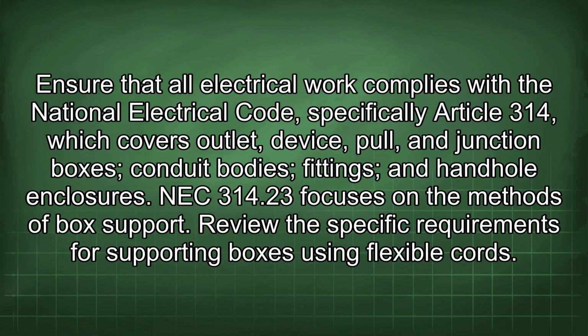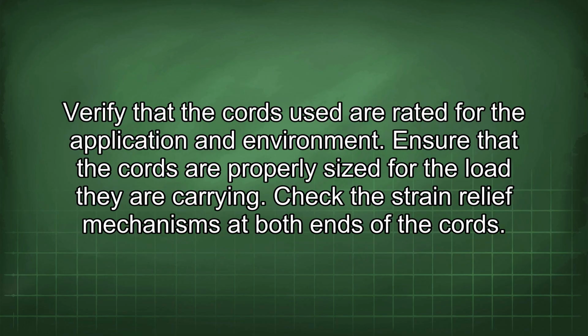NEC 314.23 focuses on the methods of box support. Review the specific requirements for supporting boxes using flexible cords. Verify that the cords used are rated for the application and environment. Ensure that the cords are properly sized for the load they are carrying.